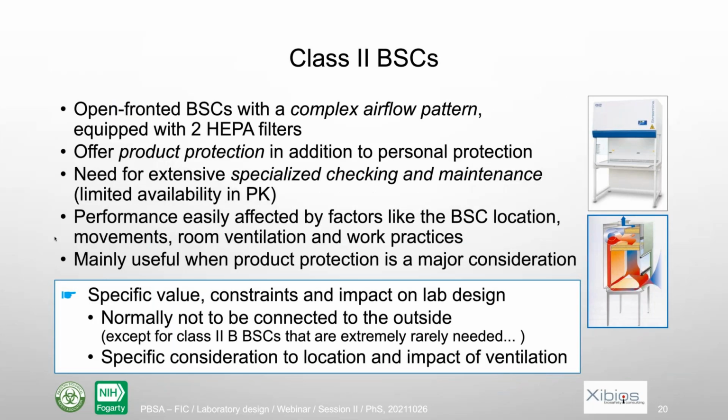Class 2 biosafety cabinets are the ones that are the most used in many situations. Why? Because of one major advantage. They also offer some product protection in addition to personal protection. There is also a fan on the top of the equipment. You see how it works on the right-hand side. The air is sucked under the work table and goes behind. Part of it is blown on the table, passing through a HEPA filter, so it's clean air. And the other part is blown to the outside, mostly, generally in the lab, through another HEPA filter.